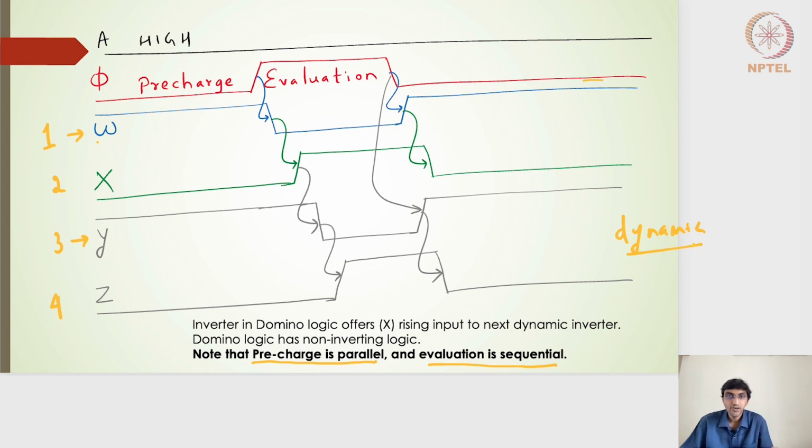Right? Hope you have understood this particular concept of starting with the ganged CMOS family, where we saw 2 input NOR gates, and then followed by the dynamic logic families, and then finally we have arrived at the domino logic, which prevents that problem of the dynamic inverters, where the falling output is a problem for the dynamic logic families, and thereby the falling output is converted into a rising output.